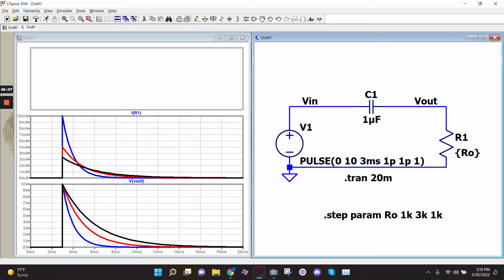I'm not super familiar with running those sims, but if you want to look into that, you can do that. There's all these different things, you can do .measure, you can do .integrate, you can do .derive. It'll take derivatives and integrals. It'll find the area under these curves if you do the integral, right? It does all this crazy stuff. I'm just not super familiar with using that. I know that you can though.